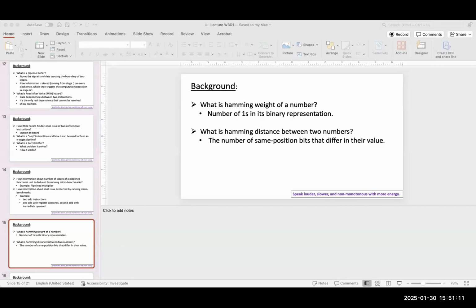They found that all of them are pipelined. For example, they observe, let me read: we report that the CPI of a sequence of either load or store instruction, free from data hazards, resulted in a sustained CPI of 1, indicating that the load store unit of the Cortex A7 is fully pipelined. Anyone want to explain this?